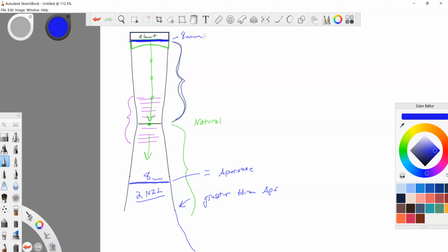313: The near zone is the only region where the diameter of the sound beam decreases as depth increases. Yeah, that's a good way of saying it. The diameter is decreasing as the depth is increasing, and that only happens in the near zone.